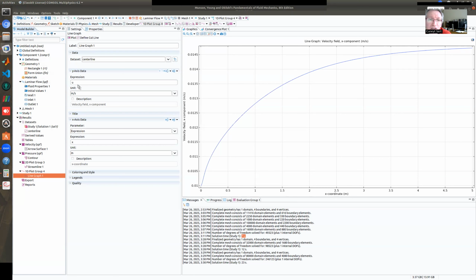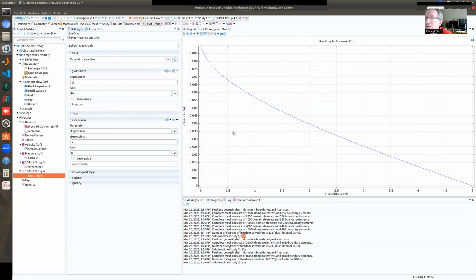And if I just change this to pressure again to see the pressure variation, plot it again, yeah, this is the pressure variation. So this part close to the end is almost a straight line. And if I extend that straight line all the way to the entrance, there is a bit of extra pressure drop here. So that's due to the flow development effects.